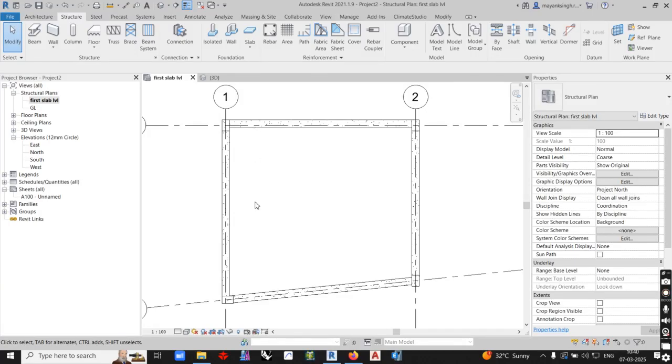Okay, in this video we're going to add several sets of beams in this direction to make it like a waffle slab. But first of all, we don't have to add and draw in each and every beam. We just need to know the center spacing and the size. Second thing, we don't want to use a rectangular beam, we have to use a wedge shaped beam.